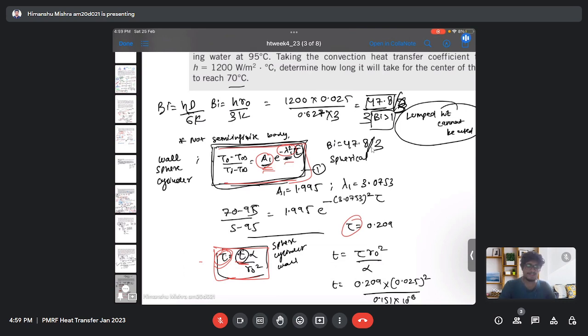For external and internal boundary layers, every case will have a specific relation for the Nusselt number, and once we get the heat transfer coefficient from it, we can use it to find the total heat transfer rate for the external or internal boundary layer problem.